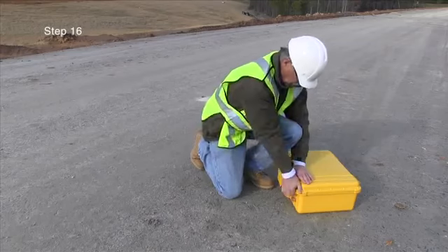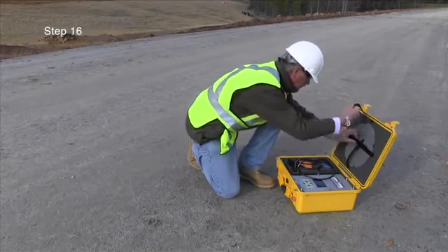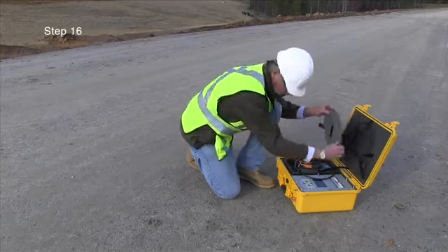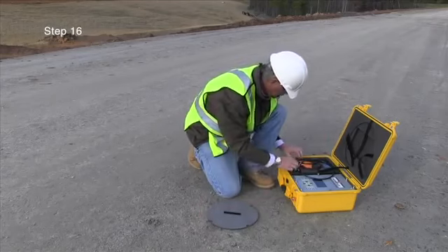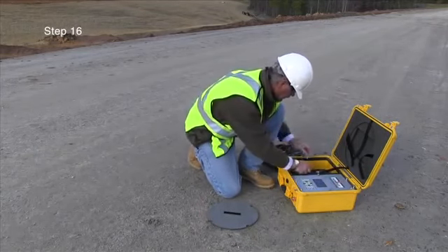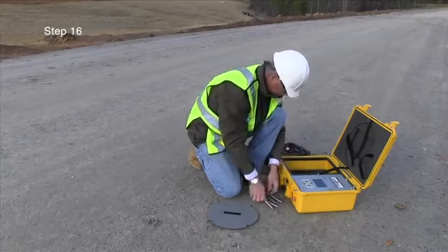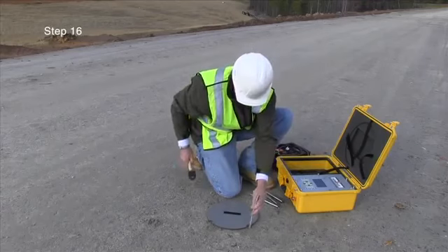To begin, place the gauge on the ground near you and open the case. Turn the gauge on and remove the gray circular dart template from the lid of the case. Place the gray dart template on the ground. Remove the accessory caddy from the EDG case and place it on the ground out of the way. Remove the hammer and the 4 darts from the bottom of the case.